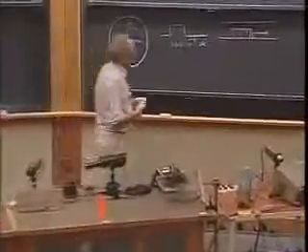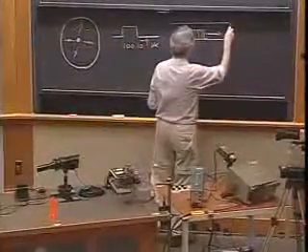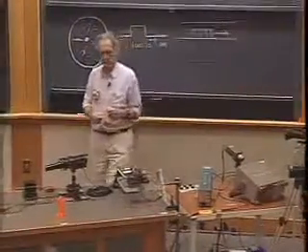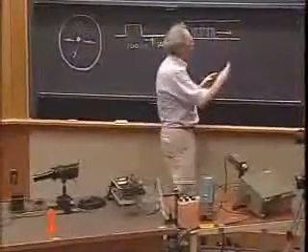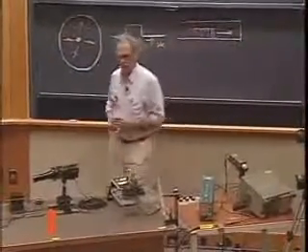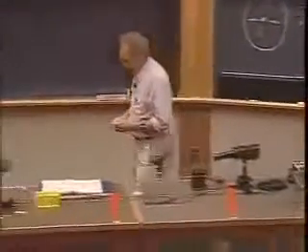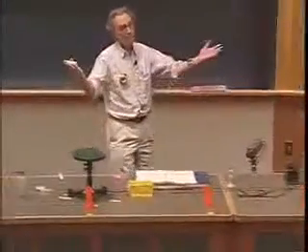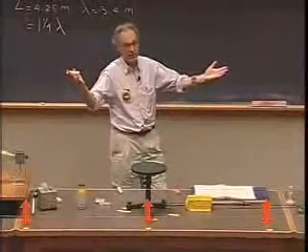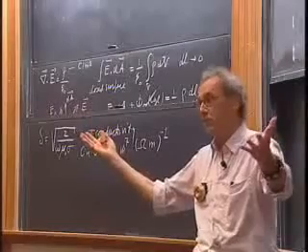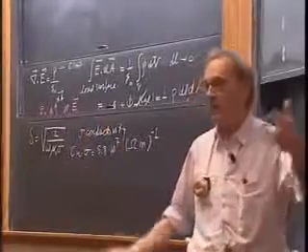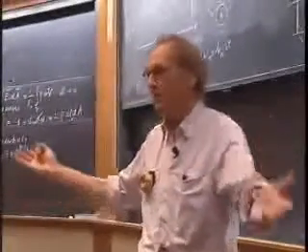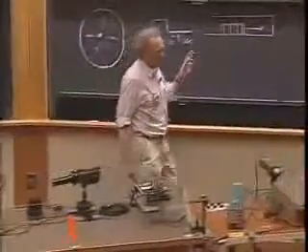Now comes the punchline. I have an option to keep this end open so that the line at the very end, so this is the inner and the outer, is completely open. And I have the option to shortcut it. And when I short it out, a mountain comes back as a valley. When I leave it open, a mountain comes back as a mountain. We're going to show you this pulse at 3 locations.